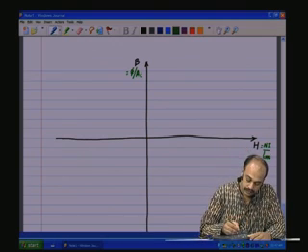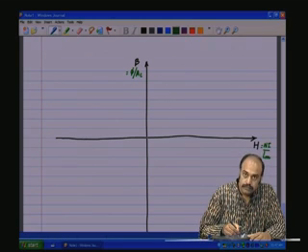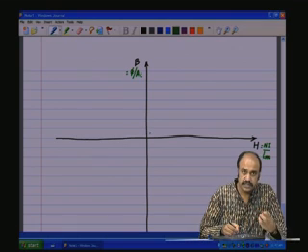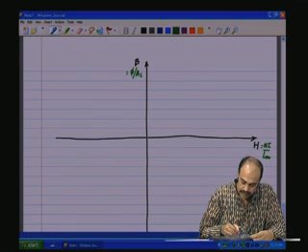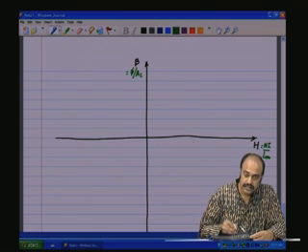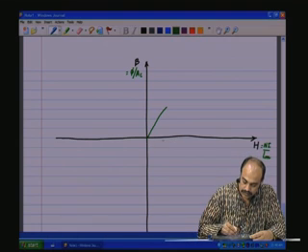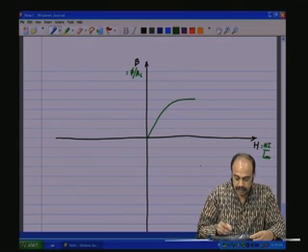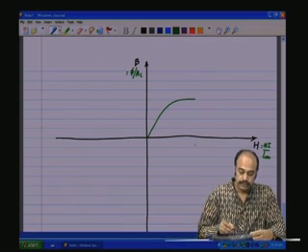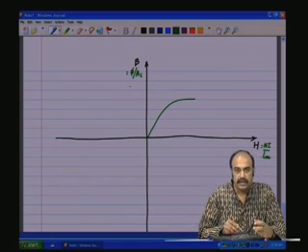So in actuality, let us say we start with a virgin specimen, a new specimen. As the field intensity increases, as the magnetomotive force increases, the flux in the core will increase. Flux keeps on increasing as you increase the magnetomotive force in the x direction. But you see that it loses its linearity and gradually it starts to saturate. So beyond a particular value of magnetic field intensity, the flux in the core will not increase any further.